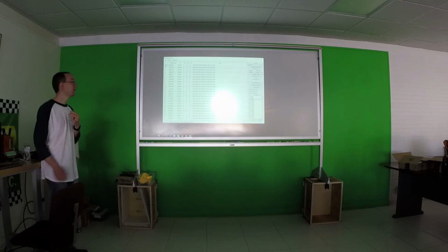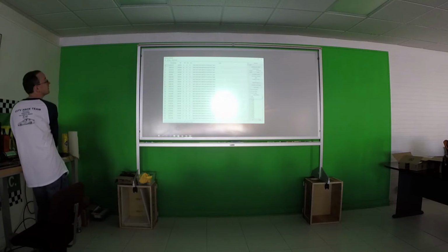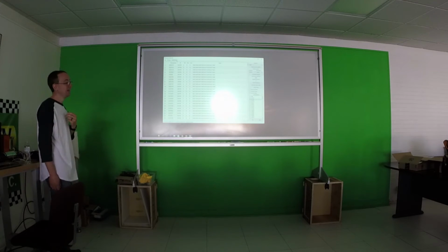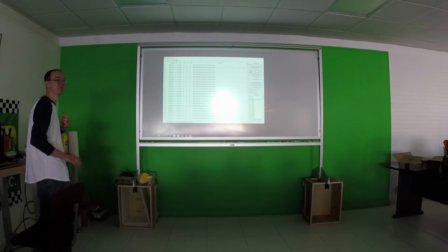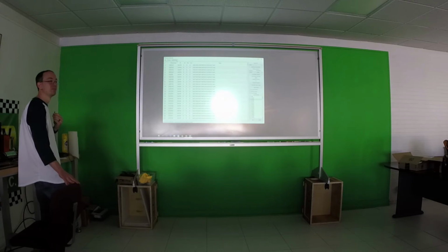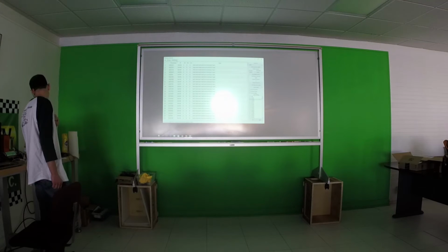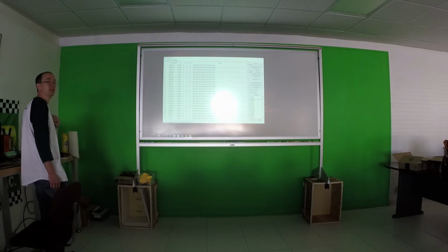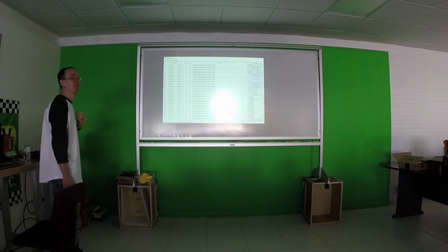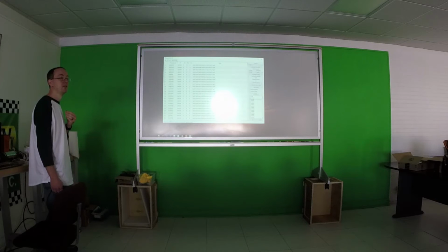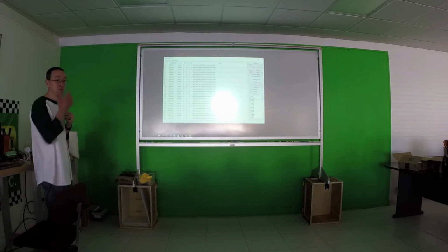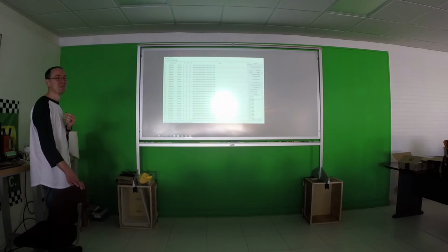It's a very good idea to be able to do that, because otherwise the capture that I had was something like 196,000 messages. That's a lot of data to process by hand. And even finding where you're at in it, one of the things we did do was take our CHAdeMO device that measures current and voltage and temperature and had it inject current and voltage and temperature into the stream. And so then I could look for voltage, and I knew what voltage the pack really was at that point. And as you accelerate, of course, the voltage changes, and so I could see the change, and I'm looking for a byte from the inverter, not from us, not from the car, that changes. So yeah, you can find various ways of injecting.